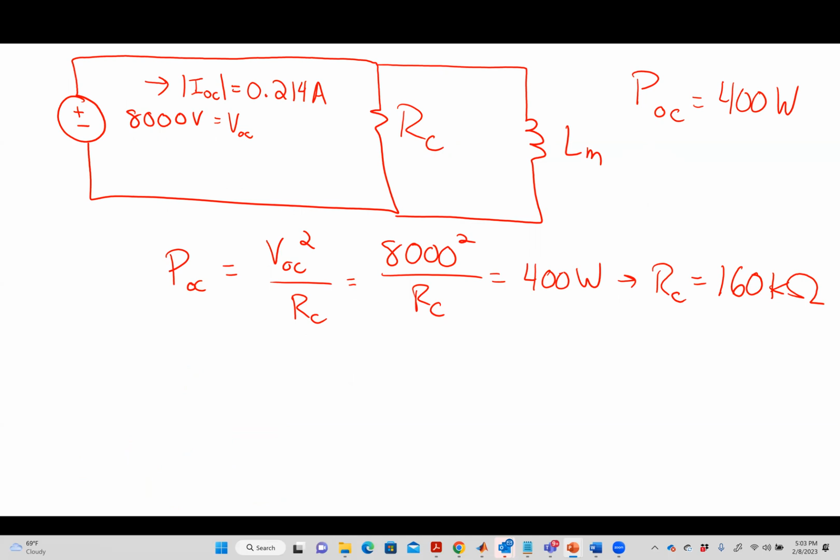A couple of ways that I could do it. Given the amount of power and the real power, can you find the reactive power? If you find the reactive power, you can find the current and do it the same way that we did resistance. How would I get the reactive power? We'll use P and S to find the power factor. So I've got a couple approaches here.